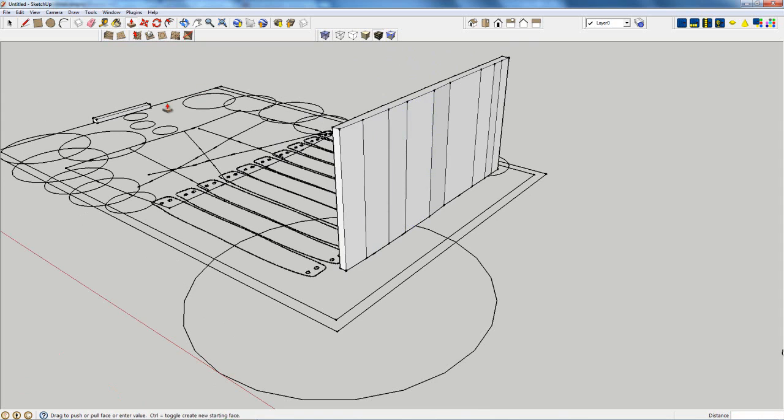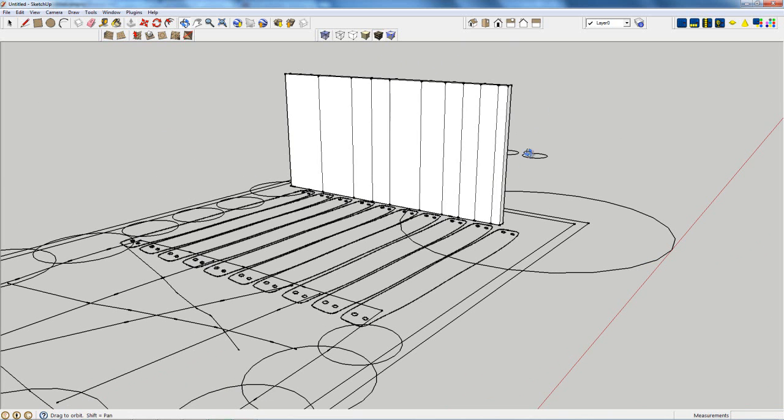So I hope you see that in the SketchUp environment, it's very easy to build a 3D model because the geometry is there. We've not had to worry at all about any size. I would do exactly the same with our decking in here, but I'd turn each one of those into a block and then copy the block across. I'd get the elevation at the right level and then move across. So once you've got a 3D model like that, it's relatively easy to dress it all up.